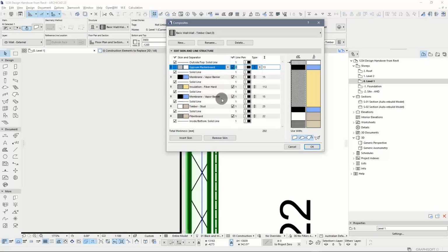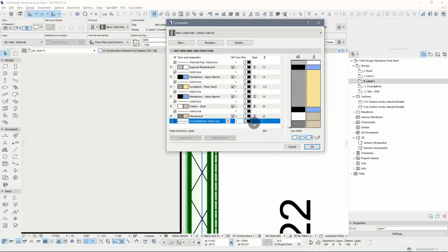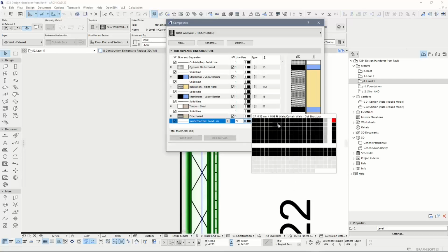Because sometimes, you'll never know if the building was put together correctly on the other side. So there might be some adjustments needed to be done, and particularly the line weights. I'm really not keen to keep all these lines in pen number 1, because I'm actually using the standard pencil tables where I have assignments for those, probably those walls on the side.